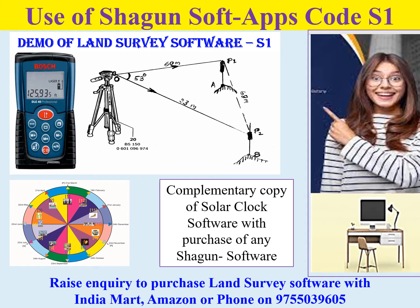In this context, a preliminary survey work plan is required for pipeline layout from the nearest seashore to pump seawater to the site selected for lake formation. In order to select the best route corridor for pipeline layout, the following engineering surveys are carried out: reconnaissance surveys through Google Maps, preliminary surveys, and detailed location surveys.